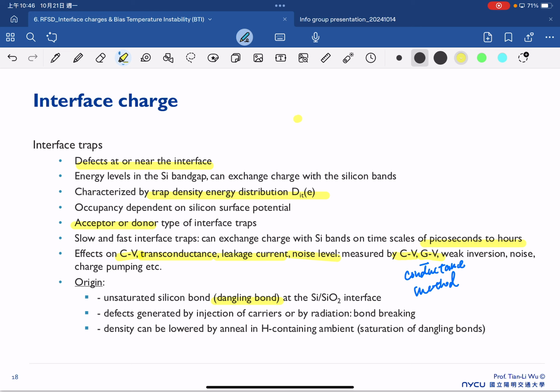That's why reliability is important, because nowadays we not only use silicon dioxide, we use very complicated dielectrics, and sometimes we do not only use a silicon substrate, we use III-V, we use 2D, whatever. Every different dielectric and substrate always causes the interface issue again, so we need to spend the effort again to understand.